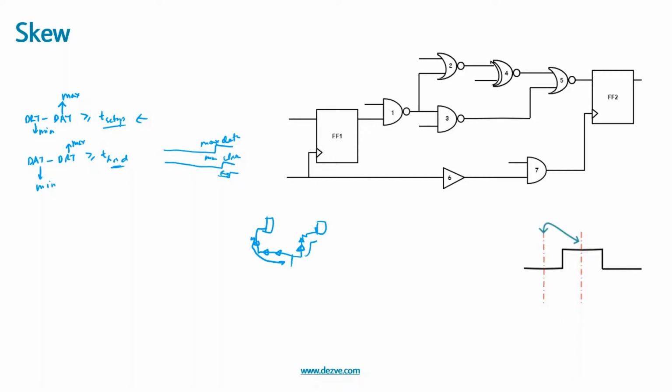When we talk about skew here, what we are telling is the amount of uncertainty we have to encompass within our design for it to work later, correct? So that's the margin we are trying to find out here. But after clock tree synthesis, when the circuit is in the physical design, we need not estimate the skew or provide margin for the skew, correct?